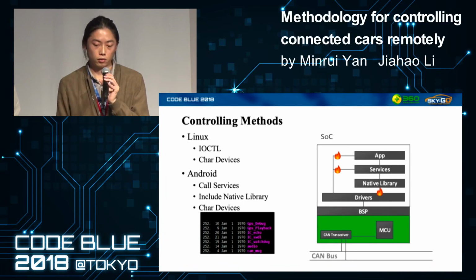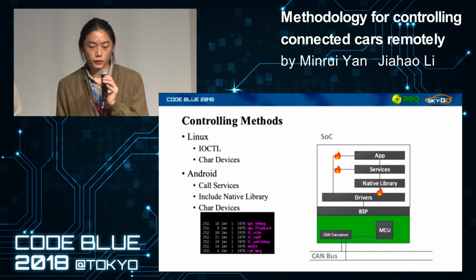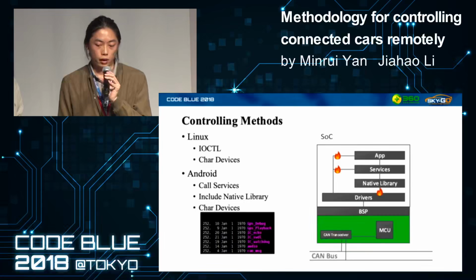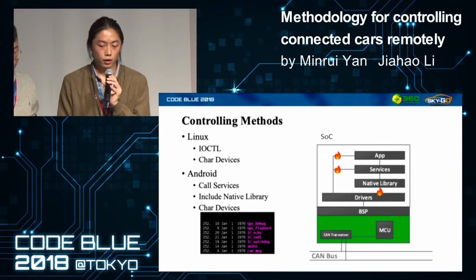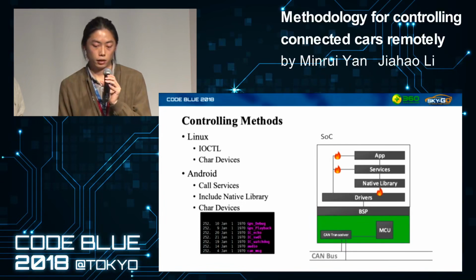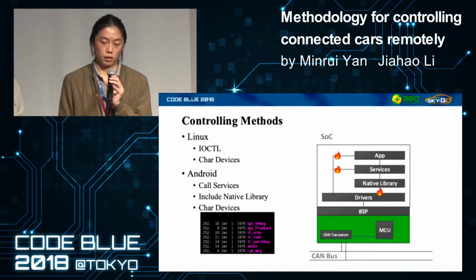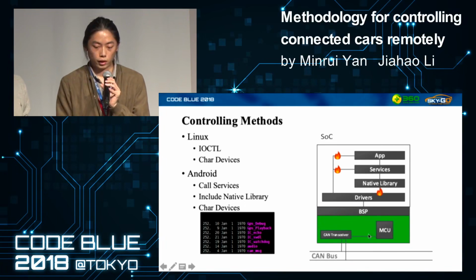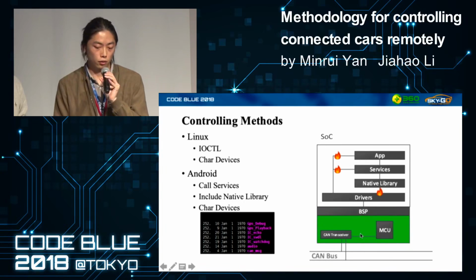You know Android is based on Linux. Because of unsafe development habits, we can access the child device with sandbox privilege. On the other hand, for example, the Android service calling source is unverified, and the library can be accessed arbitrarily. We can send a control command with low privilege, but it is not the real CAN message, it's UART data. The MCU on the bottom board will parse the UART data following the data format to send the CAN messages. So we can only send the messages predefined by the automaker.